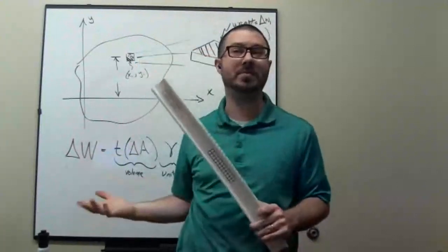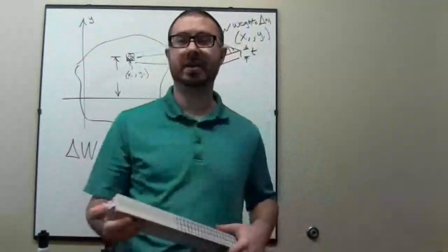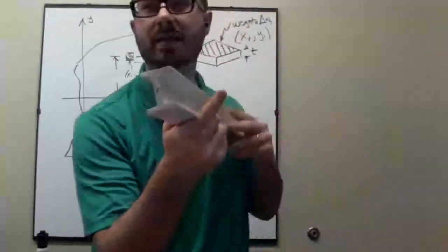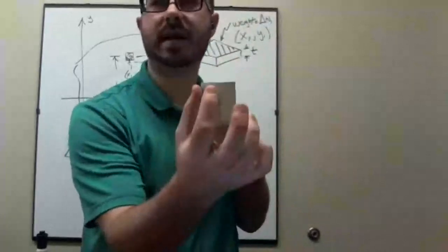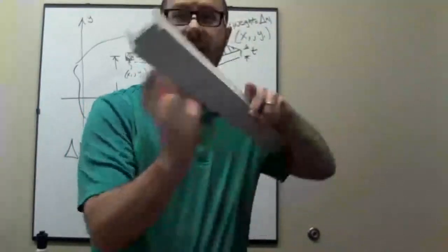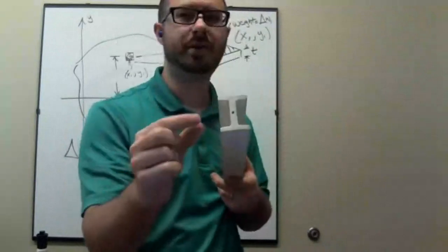But I don't know how much bending there is if I don't know where the centroid is. So locating the centroid is very, very important. Again, go back to what I was saying earlier. This would be a section of uniform material. It's all the same rubber beam. And it's also sort of uniform thickness.